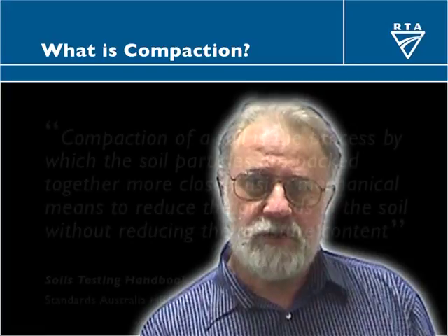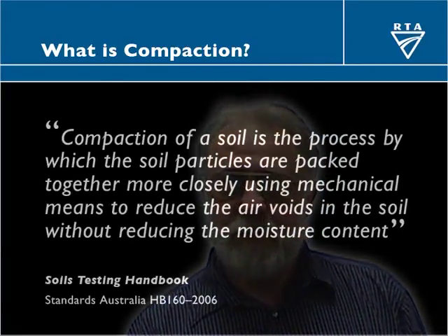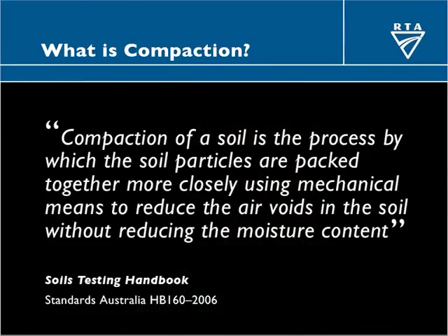It was published about 2 years ago, and it says, compaction of a soil is the process by which the soil particles are packed together more closely using mechanical means to reduce the air voids in the soil without reducing the moisture content. Now, we'll be unpacking that progressively as we go through this presentation and trying to draw out some of the practical implications.